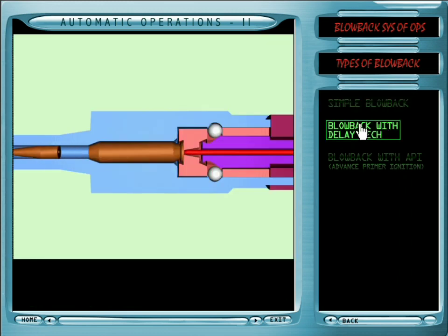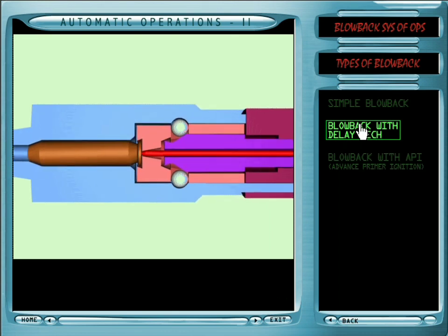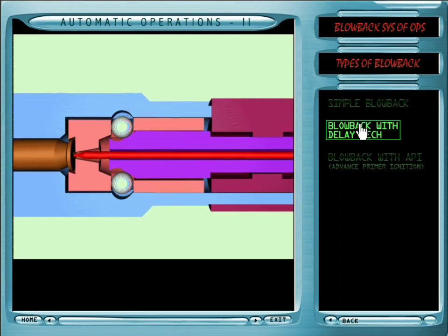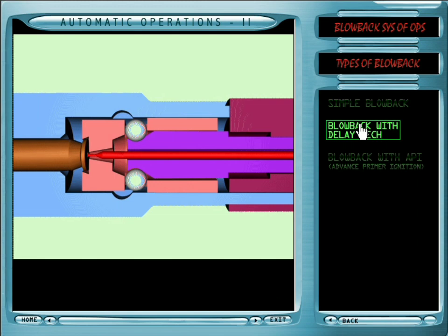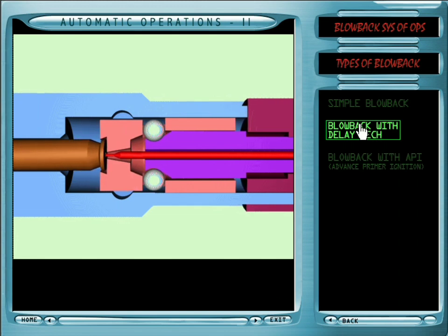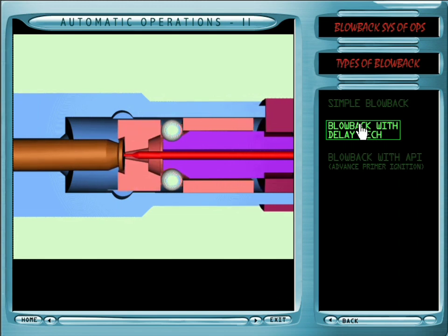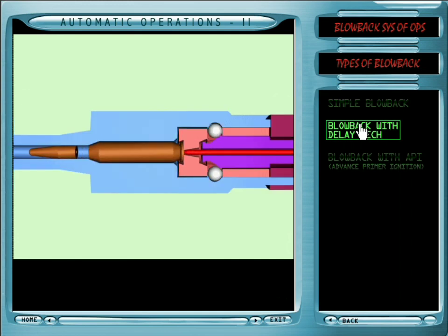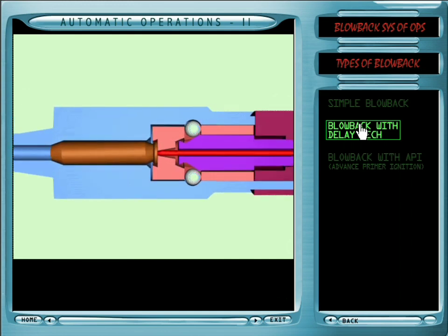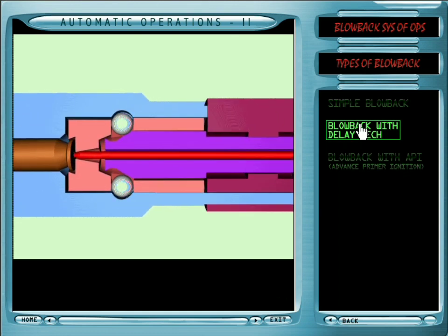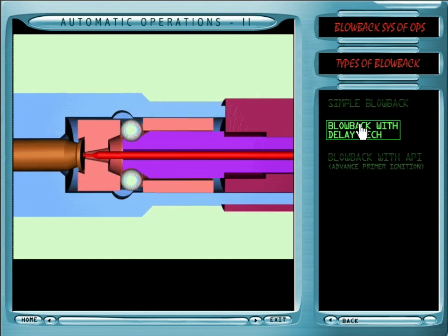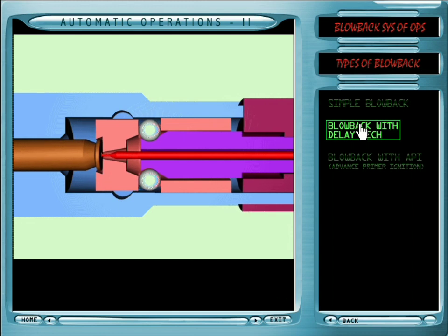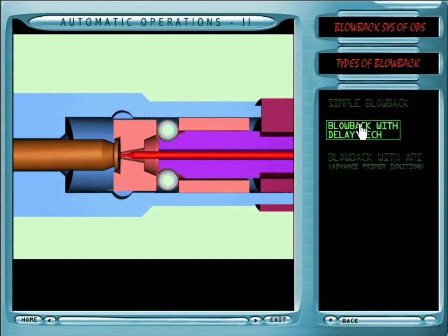Delayed blowback. Delayed blowback allows for accurate single shot fire because the weapon using the system fires from a closed bolt. An example of the same is the German G3 rifle, which operates on the delayed blowback principle. When the round is fired, the gas pressure drives the bolt backwards and so forces the rollers into the main part of the bolt. The pressure by then is low enough for the empty case to be extracted safely.